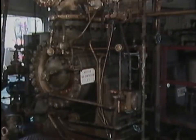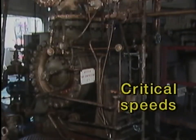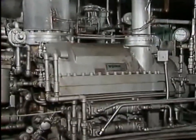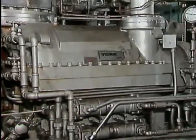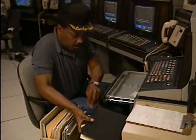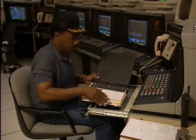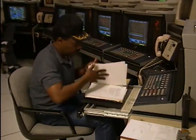However, in many centrifugal and axial compressors, certain rotational speeds, called critical speeds, cause severe vibration. This vibration is caused by the physical characteristics of the compressor's rotating parts. The vibration can be severe enough to seriously damage a compressor. Critical speeds are often identified in a compressor's operating procedures, and they occur when the compressor is at less than full operating speed.